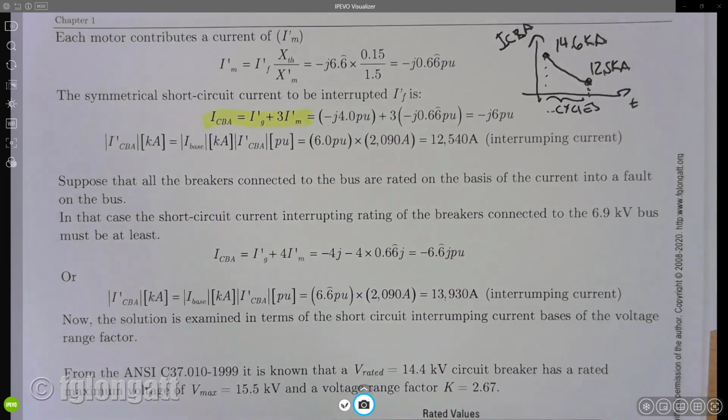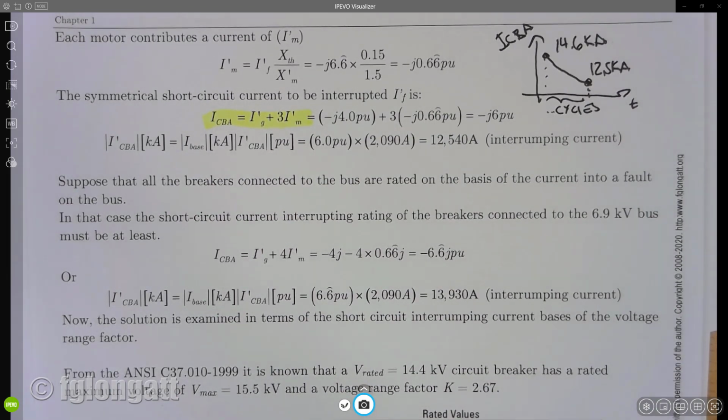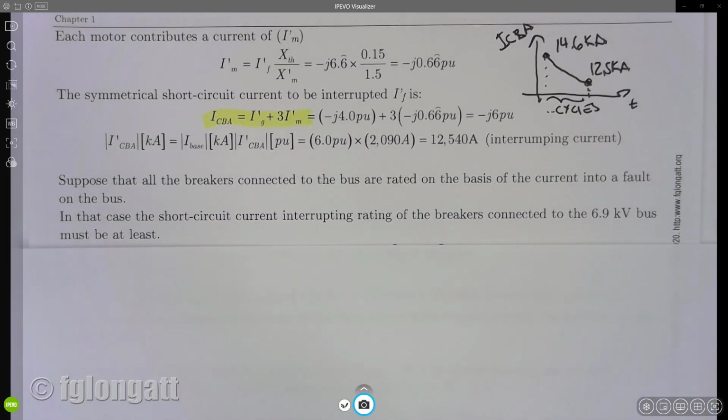And right now, the next step is the following. Now, we need to try to find the worst case scenario for the circuit breakers, okay? And if you are with me, what I would like to show you is that the worst case scenario is when the short circuit happens at the bus bar, and you will get the maximum fault current.